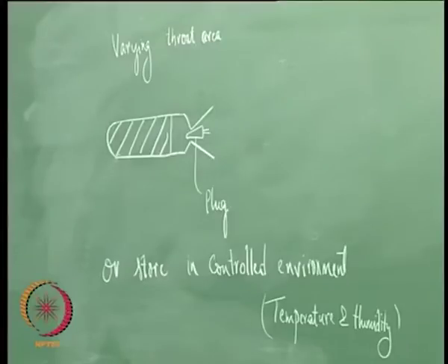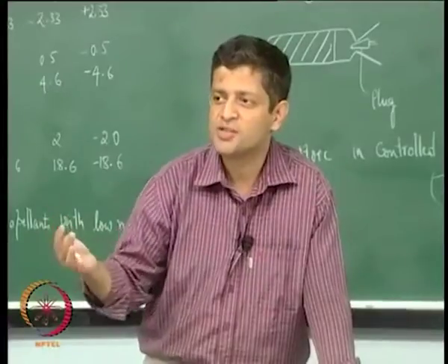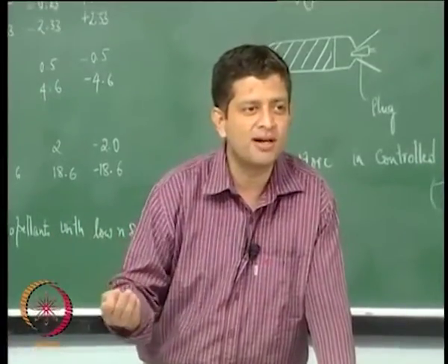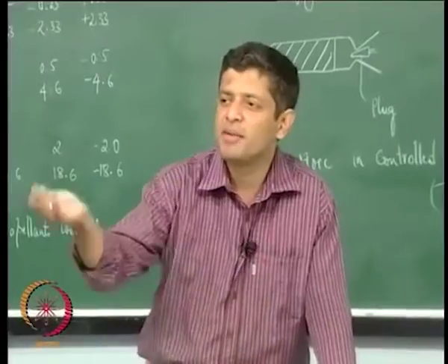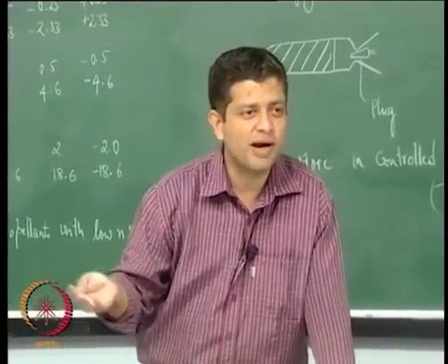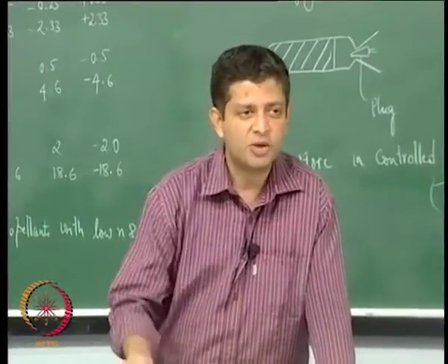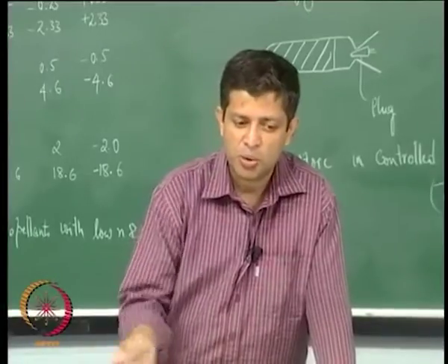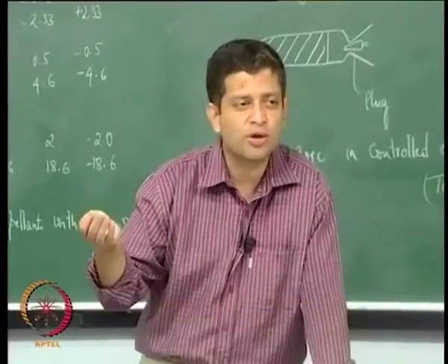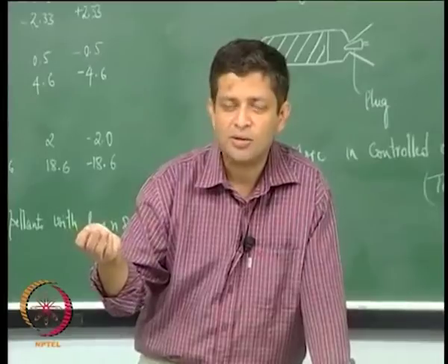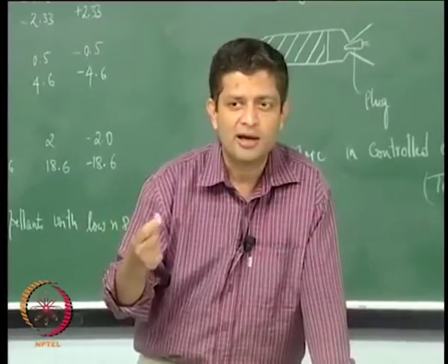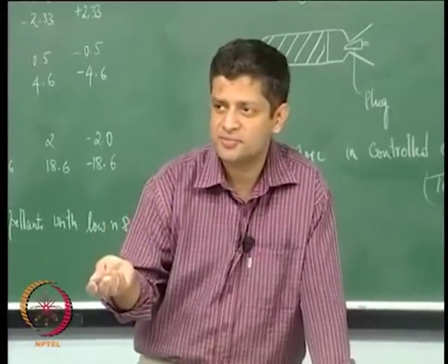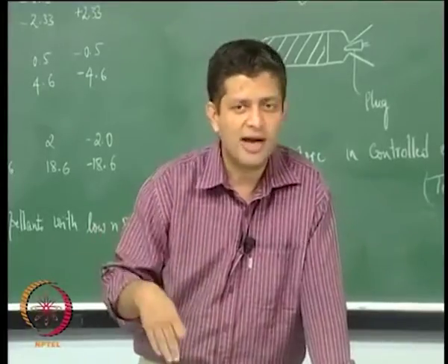These are not possible for very large rocket motors also. In large missiles, you cannot have them stored in a controlled environment and then be able to move them to the launch pad within a very short time. So what is done in such cases is you will have a small liquid rocket motor attached to the payload, which will make up for any loss in thrust, which you can cut off at any stage.